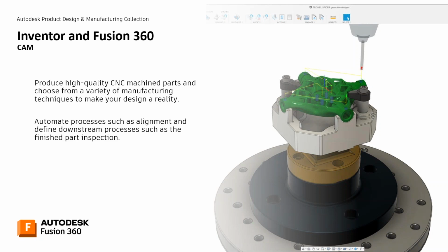So the core Fusion 360 that you get, though, can do milling. It can do that. You don't have to buy an add-on. It does come with some milling and inspection capabilities. So, for instance, I'm doing a class at Autodesk University this year on manual inspections, first article inspections with Fusion 360, things that people have been asking for in Inventor for a long time. Why can't I create an inspection drawing? Well, you can today. You simply send it to Fusion, and then you create your first article manual inspection, and then you can do an inspection recording for quality control right inside of your core environments.